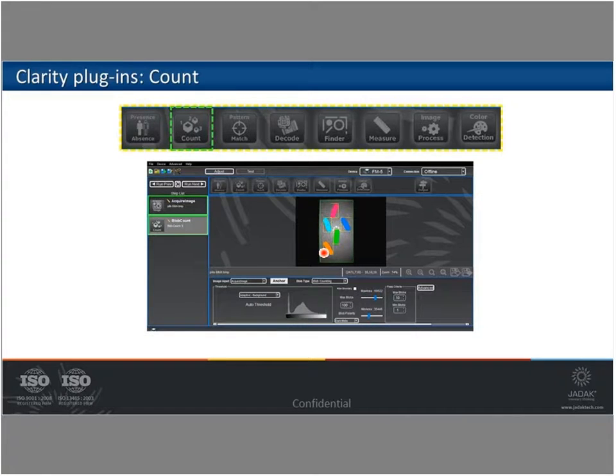Our count function, also often called blob counting or glob detection, is used to find things in the image. You're not going to identify them by shape necessarily, but just by size and by contrast, you're going to say there's a certain number of objects there in the image. In this application, I'm counting some pills, but it could be applied to manufacturing parts, screws that are in a tray, or any number of things.